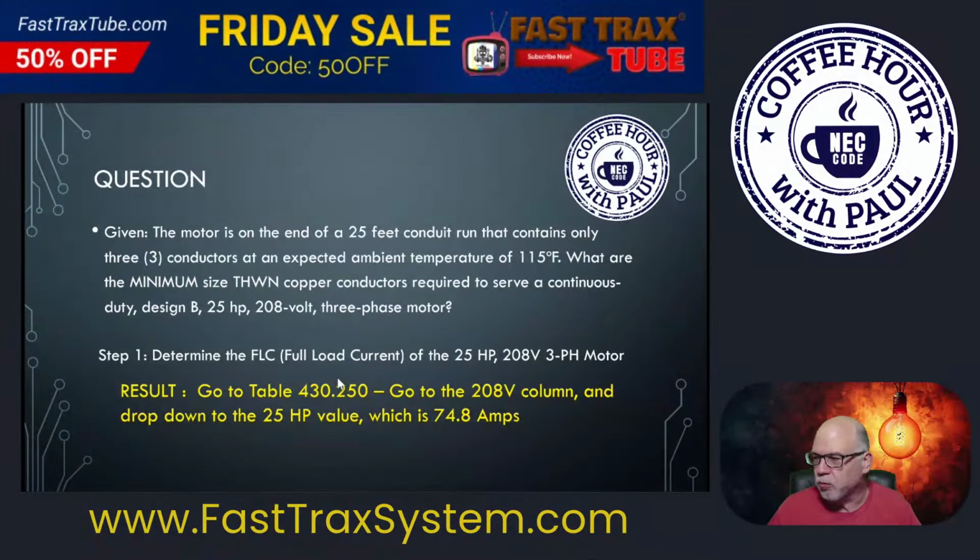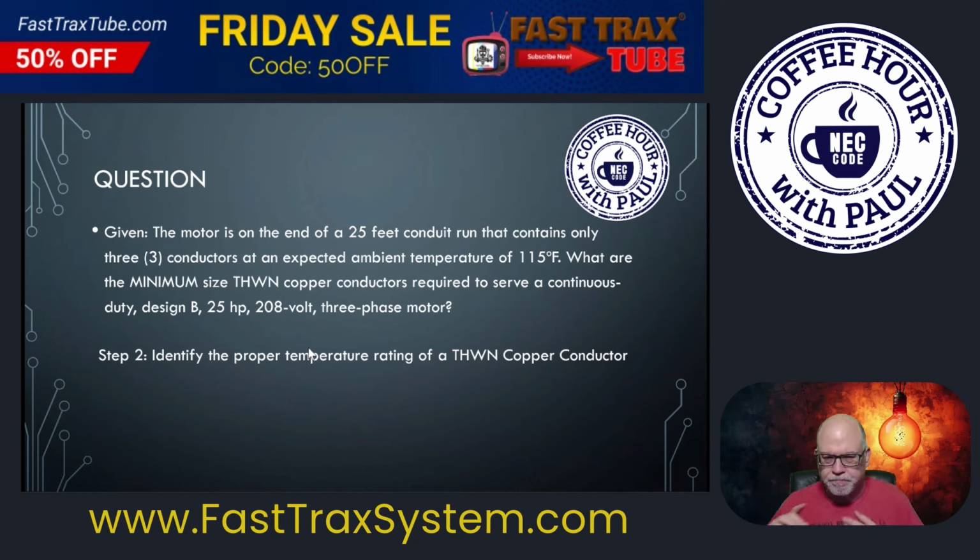All right, so we established that. We're good to go. Now, same variables. Next step is we have to identify the proper temperature rating of the THWN copper conductor. Now, this is interesting because THWN, y'all know the T stands for thermoplastic, H stands for heat, W stands for wet, and N stands for nylon. Okay, so this differs from THHN in that there's no W in there, and THHN has two H's. Two H's means high heat, means 90-degree rated insulation. One H means 75-degree rated insulation.